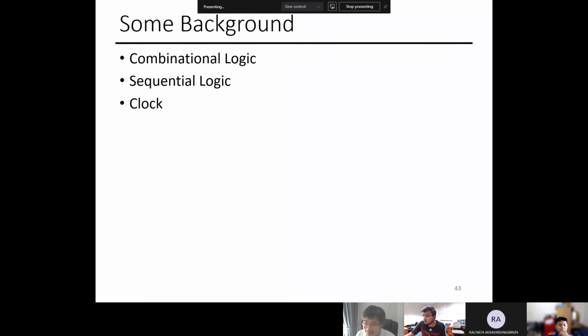Sequential logic enables the state that we see, because you can stop the clock and look at the sequential logic and see what data is in there. For example, what's the data in the register file at this moment in time, before I process the next instruction? Combinational logic, everything happened in one cycle, so that when you do an add, you get the result right away. And you store them in the sequential logic.